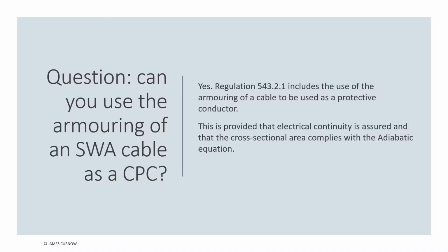So the question in this video is, can you use the armour of an SWA cable as the CPC? And the answer is yes. The wiring regulations include a list of types of protective conductor, and it is possible to use the armour of the SWA cable. However, it is necessary to ensure that the electrical continuity is assured and that the cross-sectional area or CSA of the armour is sufficient to comply with the adiabatic equation, and that's what I'm going to be talking about in this video.